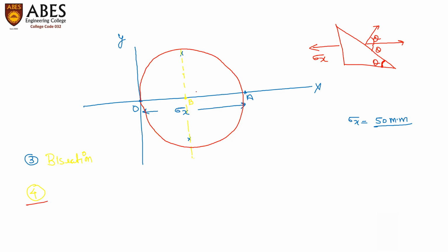And for this, we have to draw a line at an angle of 2 theta from that particular point B, in the direction having the orientation of that particular plane with respect to the stress acted on this particular direction, and that angle is taken as 2 theta.